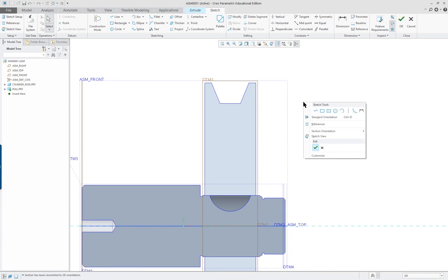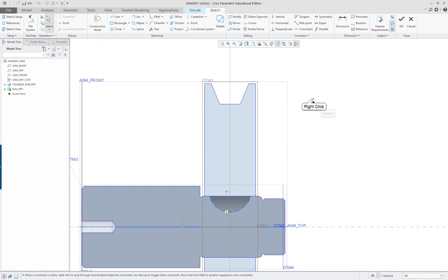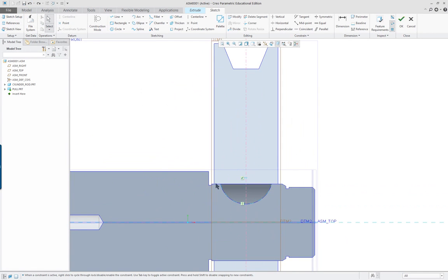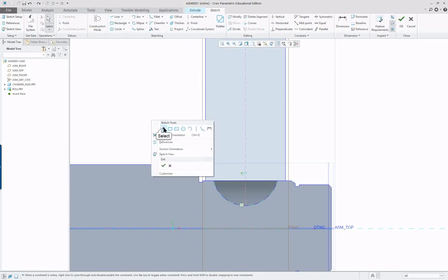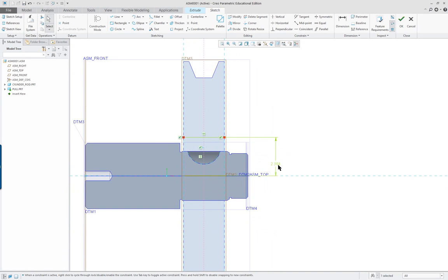Now, in this case here, it's just going to be an extrude. And I'm going to put a center line down the middle here. You can see I can pick this up. It's intelligent enough to know that's there. And I'm going to simply do a cutout. Oh, I'm sorry. I'm not going to do the cutout. We'll do that second. I am simply going to put a line in, nothing else. And I'm going to put it in. Doesn't make any difference actually. Like so.